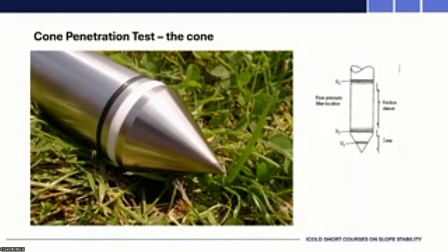You've seen on occasion the cone gets quite worn on perhaps one side. If you're in the field, you have the opportunity to inspect the cone, because if that happens, you can start getting the cone deviating from the vertical when you're penetrating. Then you think you're measuring vertically and you're actually measuring at 45 degrees. These days, most contractors have an inclinometer, so they can ascertain they are pushing vertically. There are some classic photographs from the early days in Holland of people pushing a cone in, and a motor car 10 meters away is being lifted off the ground, because the cone has done a complete 180 and come up under the car and is pushing it up. So we're trying to avoid that.